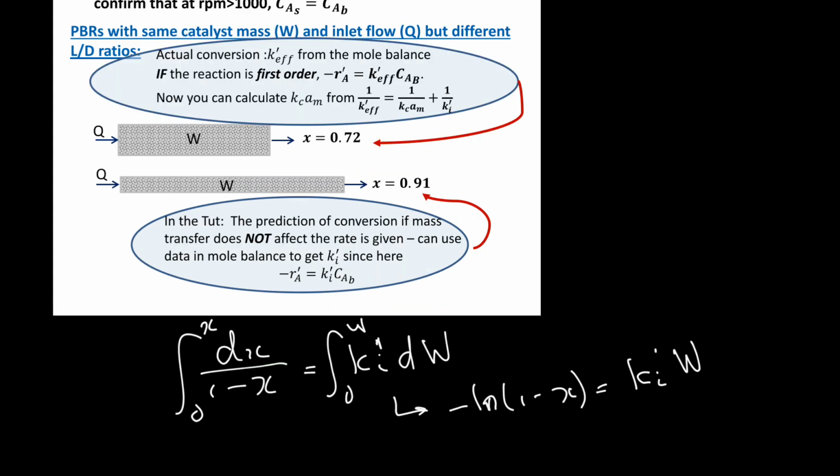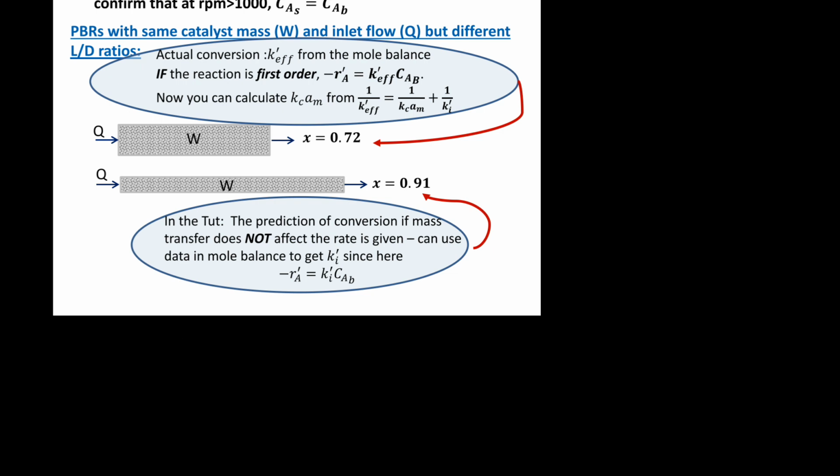Conveniently, you were told that it is a first-order reaction, so it's an actual first-order reaction, which implies a few things for our analysis. The first important thing, it's actually easy for a first-order reaction, if this rate constant is an unknown, to perform analytical integration and not a numerical technique. So then you can end up with an equation in which you can just substitute that 91% in order to calculate your intrinsic rate constant.